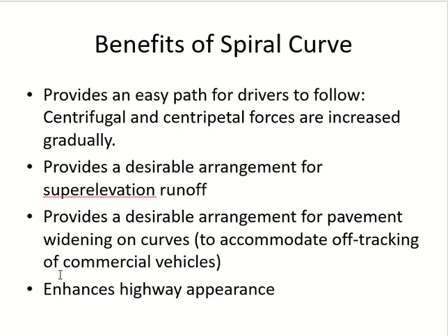So he's turning, right? He's on the curve, but not the main curve, but the spiral curve. So it provides you the space to achieve the super elevation. It provides you a space for doing the widening of the lanes as well. Okay, on high-speed roads again, we have to increase the lane widths. Why? For who?